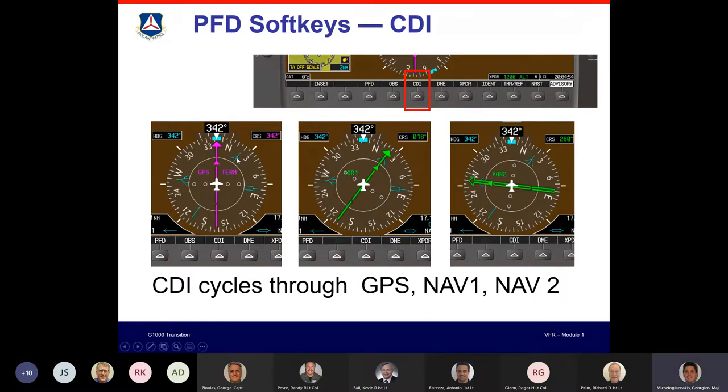Can anybody tell me what those light blue needles are? I believe that's the ADF. Isn't that the VOR? No, I'm sorry. Is it magnetic based? A turn. It shows the direction of a VHF signal, but not necessarily. It differentiates between that and the course bearings that you set up. It shows the VOR that you aren't actively tuned to with the CDI.